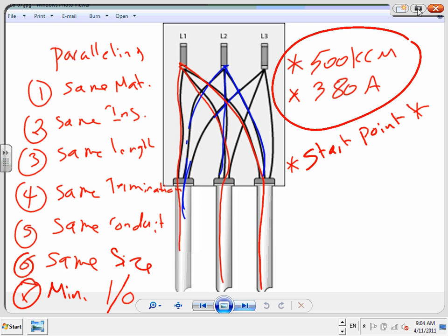Is it going to transfer within 10 seconds like you said? If it transfers, check, yes. Is it going to go back within 15 minutes as it's supposed to? And they wait for 15 minutes, guys. If it goes back, check, it works. So they verify every single operation, and they write an operation manual for the owner.